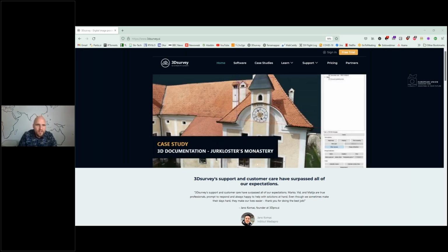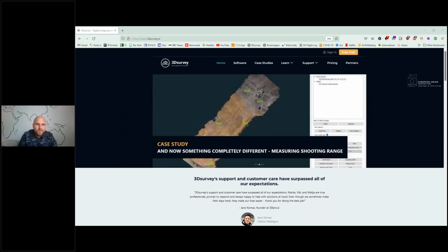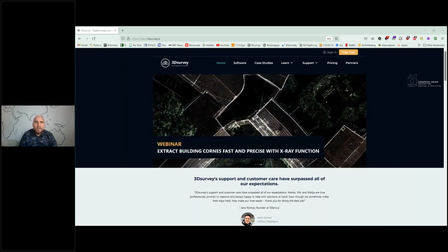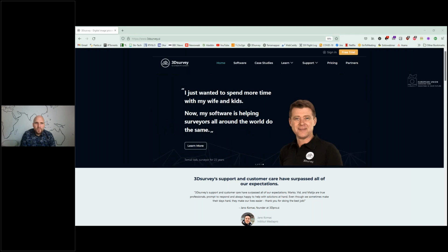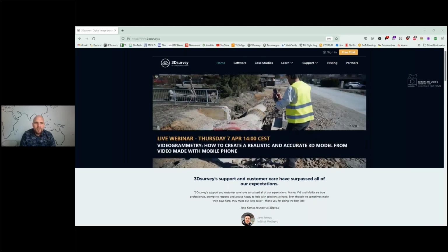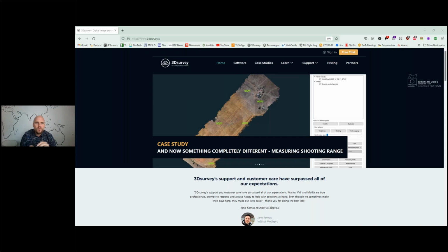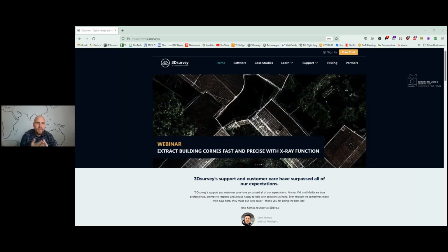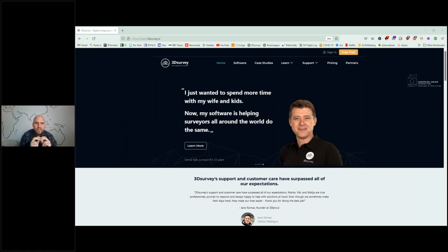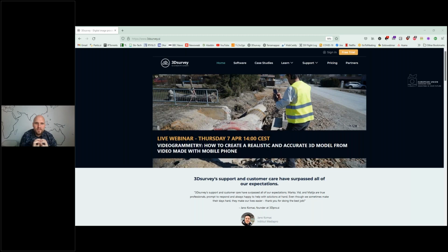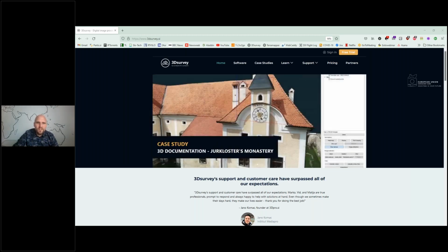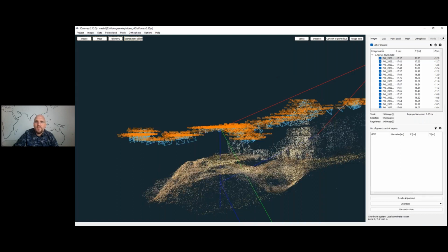Okay, Mr. Hussein is asking, can you please let me know which application is used for the whole process? Okay, maybe this one was not clear enough. This whole process was done in 3D Survey. The video itself was recorded on a phone, so it can be recorded on an Android or on an iPhone device. It can also be recorded on a handheld camera. This doesn't matter. But then once we get the video, we go into 3D Survey, we go to images, extract images from video, and then we just continue with the process. So the whole process from recording video onward to orientation, everything is done in 3D Survey.